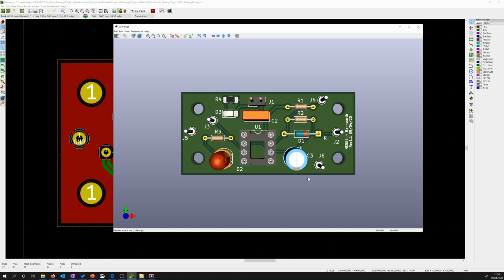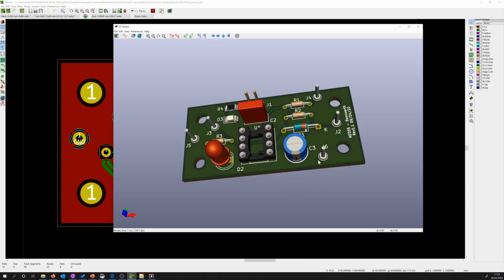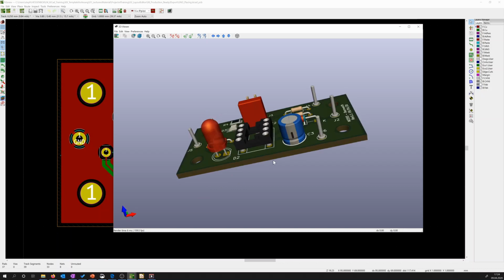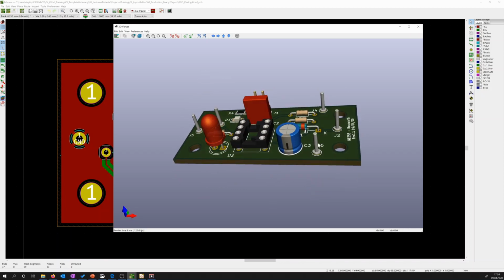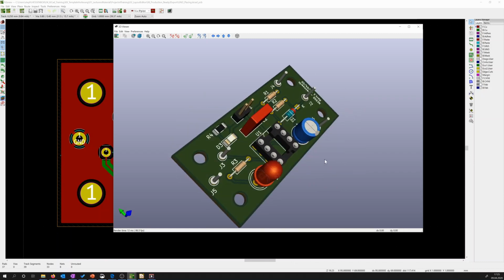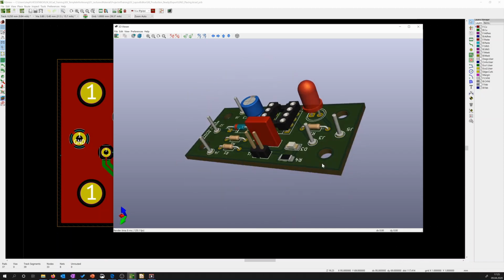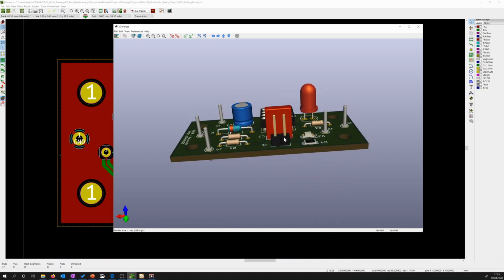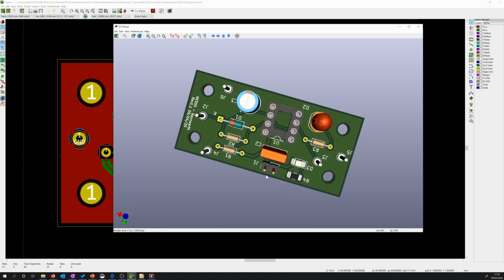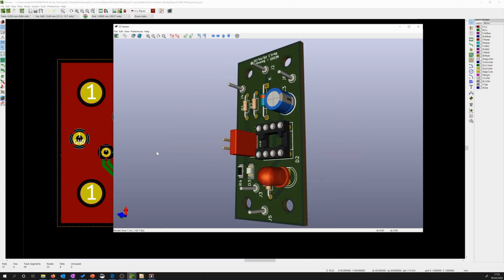We have here our socket, our C2 capacitor, our two surface mounted devices, our pin headers, capacitor, and the pins. We can turn them a bit, and you see, thinking about access, if you have here the screw heads, you still have the possibility to access these pins for testing. Also, on this side, you have a screw here, you can access from this side, and the small SMD parts you can access from this side or even over the screw. Here you have the pin headers for connecting the power supply and our stabilizing capacitor.